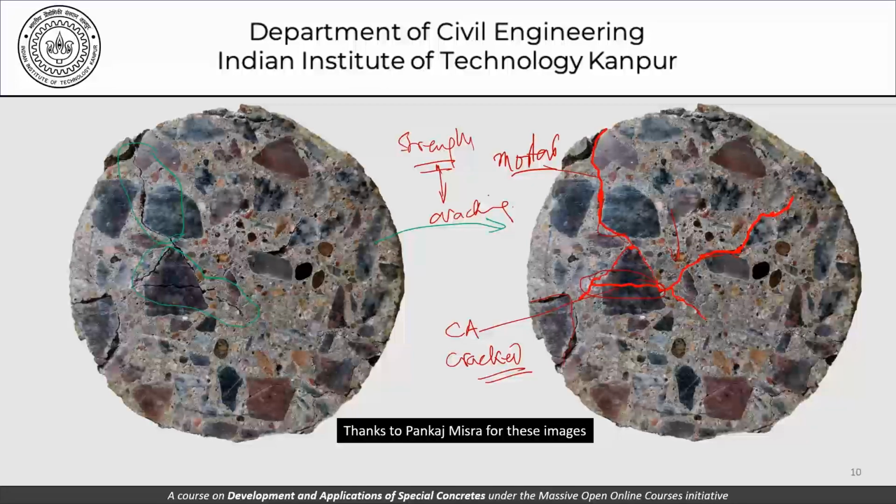Right? Since they are related, and crack propagation is taking place through the mortar, that really gives credibility to our belief that strength is related to water cement ratio. Now, what does water cement ratio do? Water cement ratio is the parameter that governs whatever paste and mortar you used.